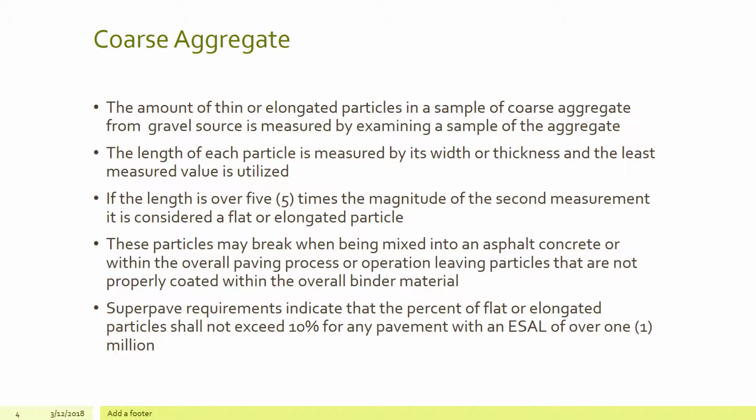Superpave requirements indicate that the percent of flat or elongated particles shall not exceed 10% for any pavement with an ESAL of over 1 million. And again, what we're looking at is that as a particle gets longer, it's going to snap on us, and if it snaps, it's going to create a failure problem within the pavement, and this is what we're trying to avoid.